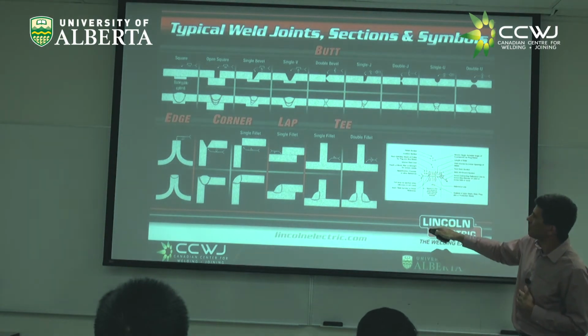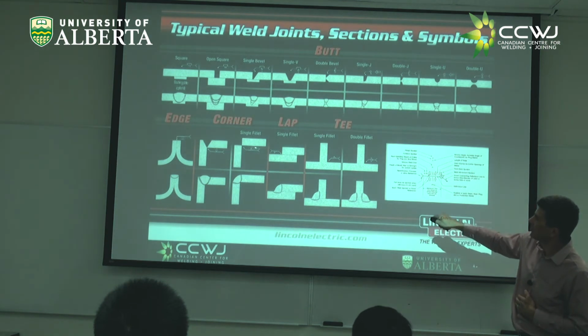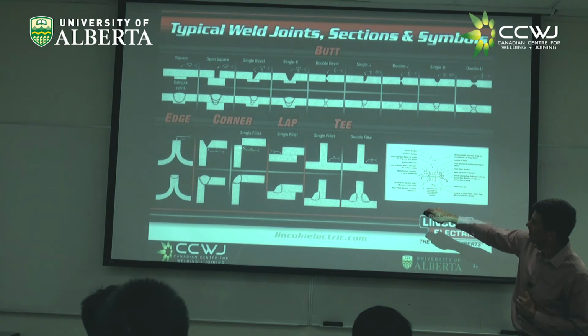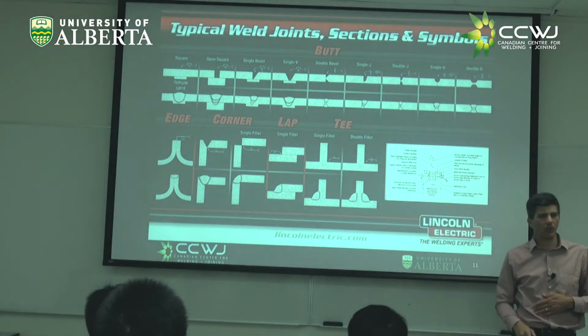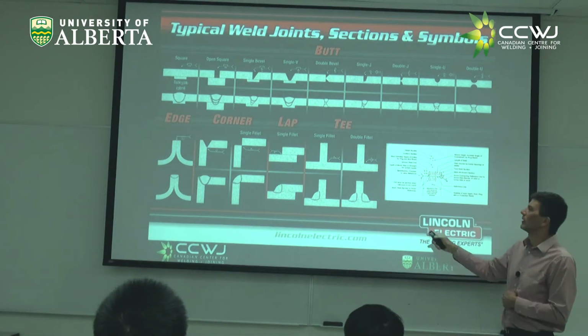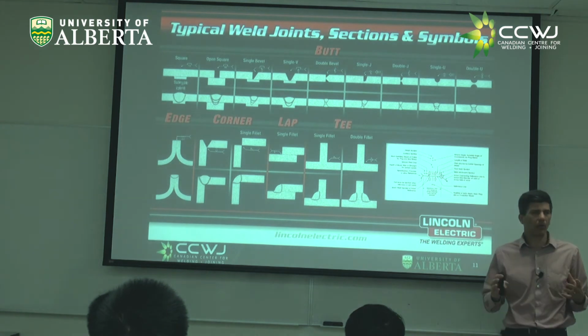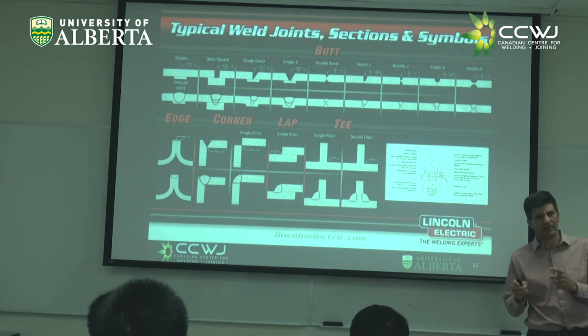Let's go to here, corner joints. Corner joints, you typically have fillet welds here, right? This is a V joint, a V groove, right? A single V here. But this, when you weld from inside, right, and the corner is what makes your groove, that is called a fillet weld. We're going to have a whole unit on how to size a fillet weld.